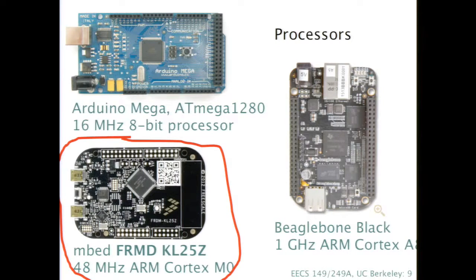And this thing comes with an image of Linux that you boot up. If you write a program under this image of Linux, it will fail to drive those LED lights. You're going to have to use the bootloader and write raw code if you use that, and that's probably not a good choice. This guy, on the other hand, you're going to be writing low-level code. But this is a 32-bit microprocessor as opposed to an 8-bit microprocessor, so it's a little bit more beefy and faster than the 8 megahertz or 16 megahertz Arduino processors.